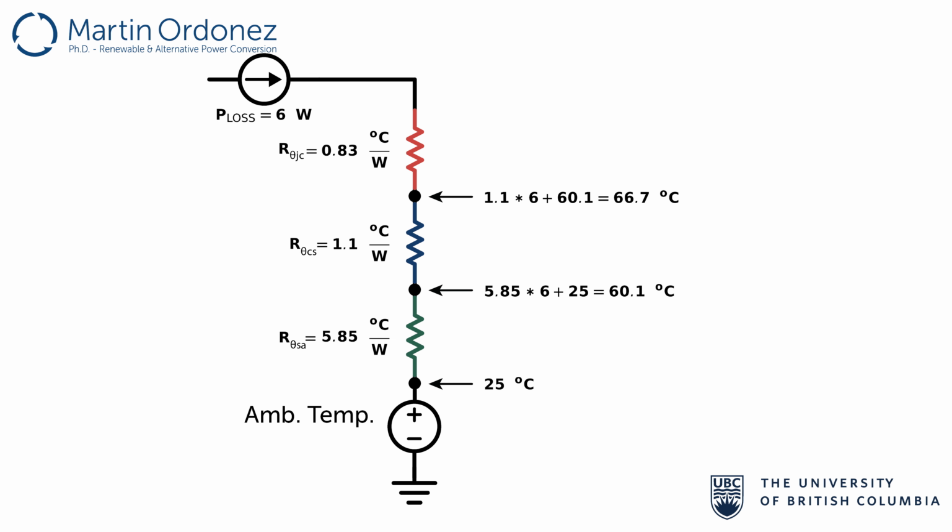By doing the same procedure, we reach 71.68 degrees Celsius for the MOSFET junction's temperature, which is about 47 degrees higher than the ambient temperature. Remember that by using natural cooling, we got to 100 degrees Celsius. So, as you can see, you can manage the operating temperature of your device by determining a proper heatsink before doing any experimental work.